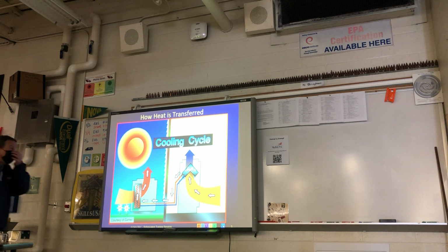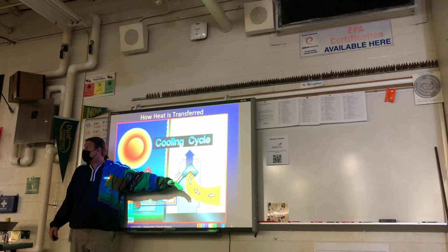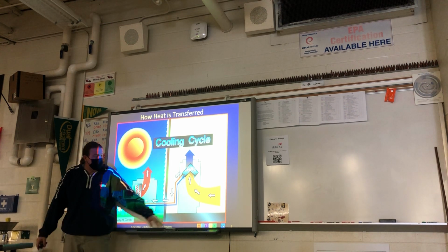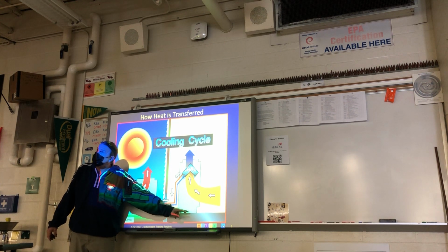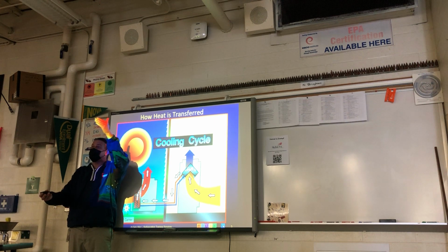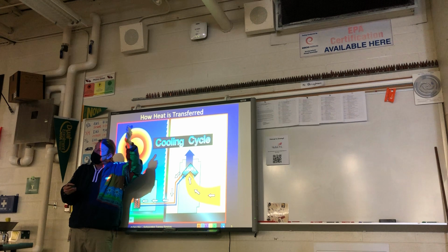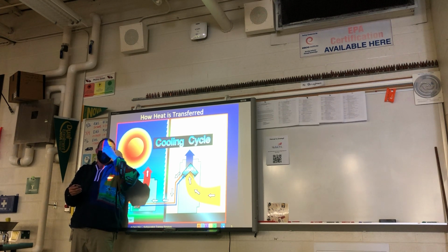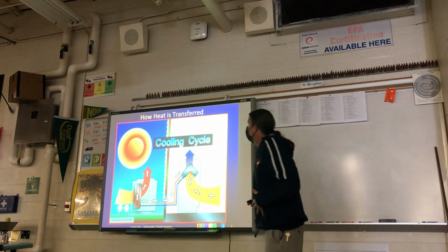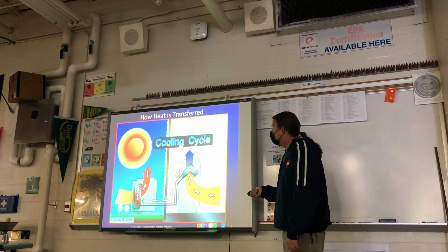So that's supply temperature, and they call that the spread. That's how home inspectors check to see if the AC is working without putting any gauges on it. After the AC's been running for 10 or 15 minutes, they put a thermometer where the supply and the return is, and if it's less than 18, there's a problem. And if it's more than 20, there's still another problem. You don't want it to be too cold either. That's called the spread, the temperature difference. We're going to bring it up a little later, but that's our delta T.